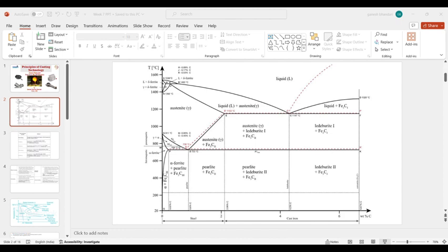And the main disadvantage of water is that water has an evaporation point of 100 degrees Celsius. And you are going to put your casting from 900 or 950 degrees Celsius straight into water. So what will happen? A lot of water will evaporate, and very high steam generation will be there, and that is not good in industries because that will create a corrosion problem. Your machinery will corrode very early.